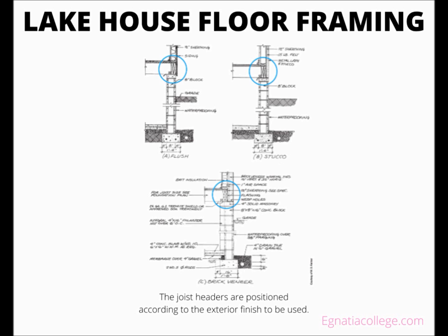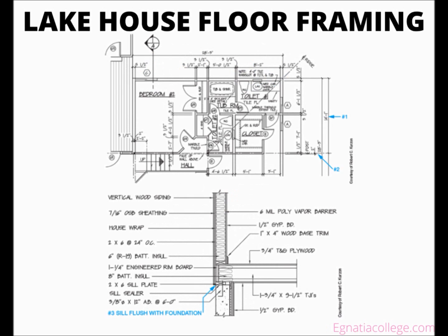As each area is framed, the carpenter must identify the following: joist headers, to locate the outer ends of joists; bearing for inner ends of joists, beams, walls, etc.; size and type of framing materials; length of joists; spacing; framing at openings. The joist headers are easily identified on the framing plan, but their exact position should be checked on the detail drawings. They may be set back to create a brick ledge, to accommodate wall finish, or to be flush with the foundation.